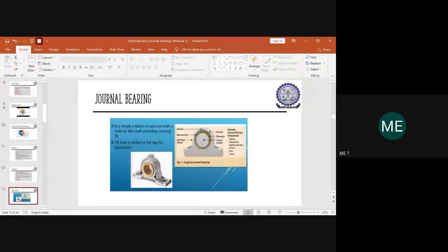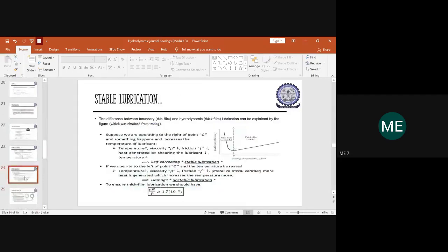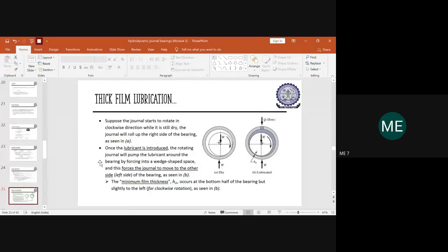So I have shown the sketch of how a journal bearing looks. If we go back to the diagram, you have a casing, which has the shaft here. Around that you have a bearing liner. In between there is a clearance through which the oil from the inlet passes, forming the required lubricant film. The shaft itself is termed our journal. So we have discussed the components associated with the bearings. Now let us go with the nomenclature before proceeding.